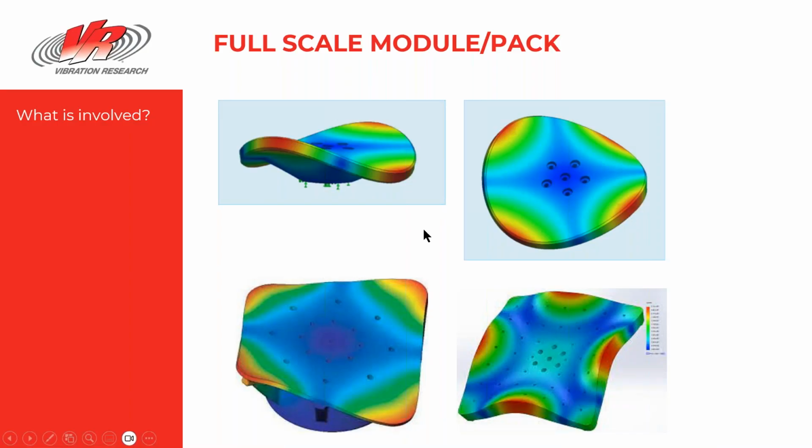Okay, so just making sure that you're understanding, when you've got head expanders, these are what I mean by the mode shapes that are occurring. So these are the different modes that head expanders are going to go into. You get more and more complex mode shapes as you increase frequencies. But you can see generally you're always going to get the higher amplitudes around the periphery of the head expander. The center at certain frequencies won't move at all while the edge is flapping away. So it depends on what frequencies and mode shapes you're dealing with.